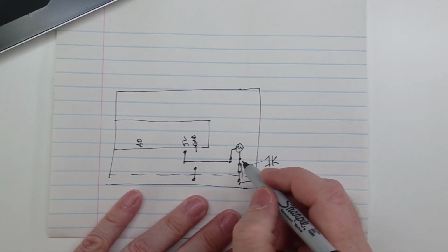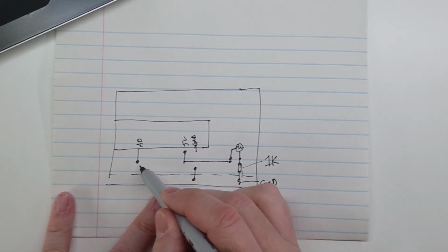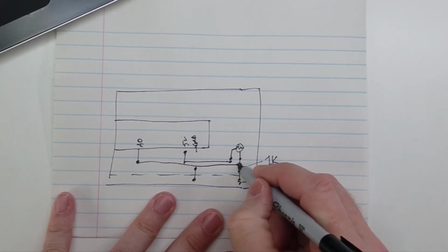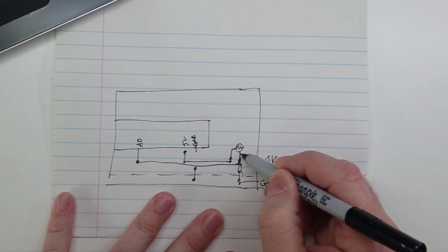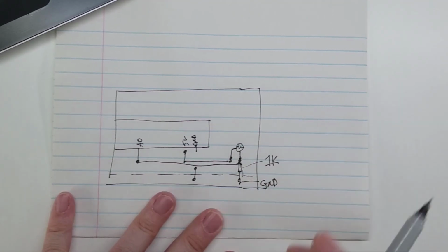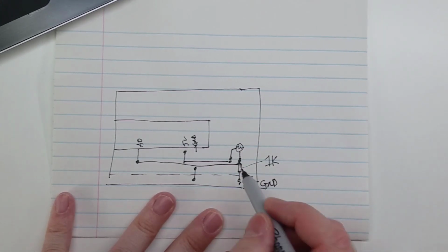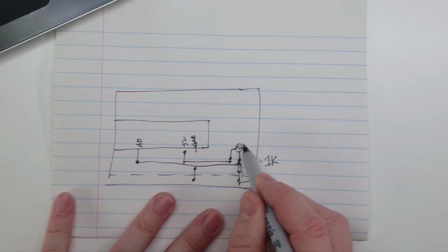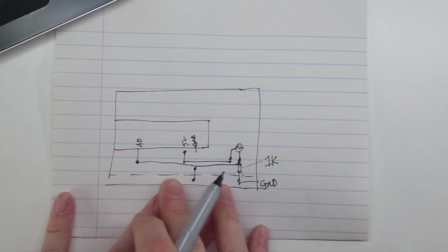Now what we're going to do in order to do that voltage divider is we're going to take a pin from the A0 and we're going to put it right here, right in between these two. So it's going to be between the photoresistor and the ground. Anywhere within that strip here on the breadboard will work. But this now takes a tap out of that as a voltage resistor, and now we'll be able to read it. So that's how that'll get wired up.